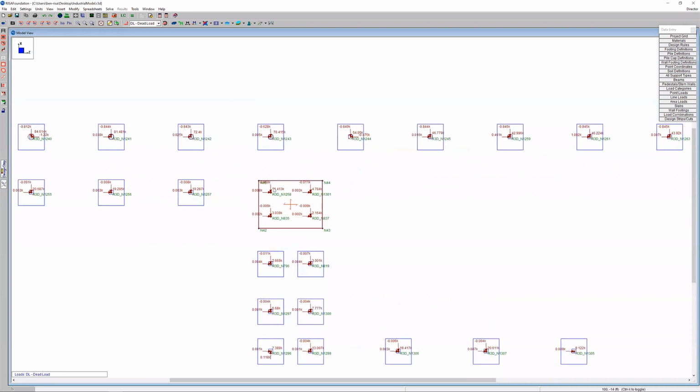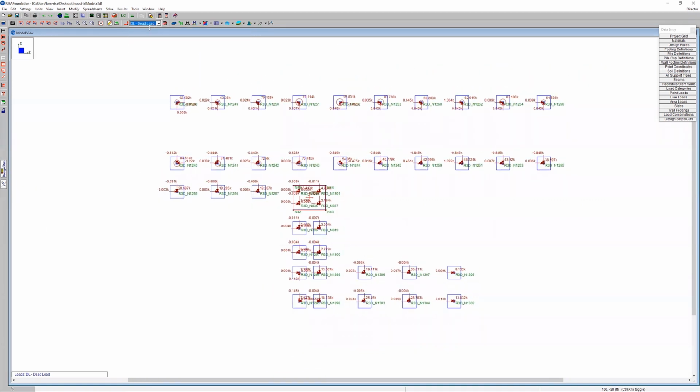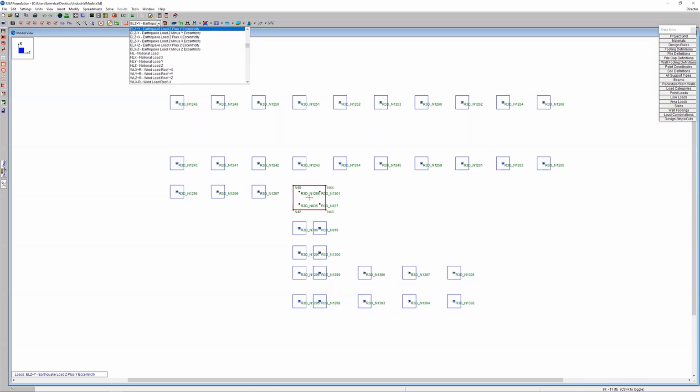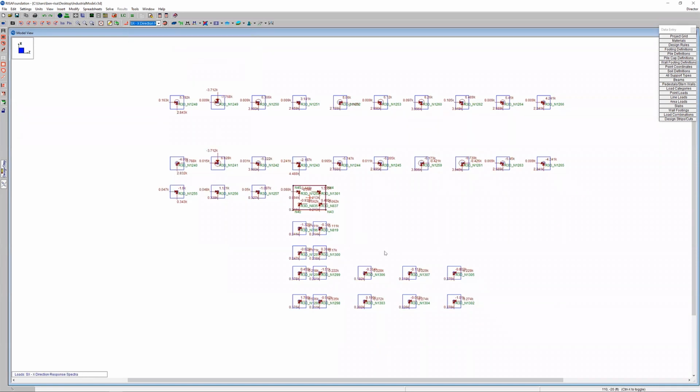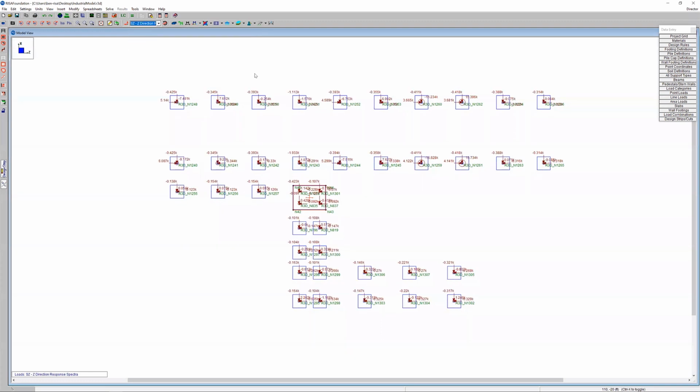And in this particular case where our columns were really close together, we created a big combined footing. When we look at this, we can look at our dead load, but also start to look at our seismic load. We don't have any seismic load generated by the seismic load generator or the ELF procedure, but we do have seismic loads generated by response spectra. So if I look at SX or SY, we don't have anything because we didn't generate that, but SZ, we have that as well. So we have those seismic provisions from RSA now included on these boundary conditions in RISA Foundation.